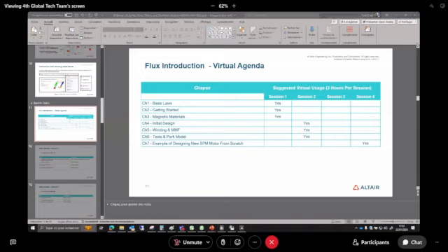Yeah, I have a question from Mayur. What about the mechanical stress? How do we check that? Suppose the rotor is rotating at a certain RPM, how do we check that? Yeah, the mechanical stress is something we don't bring directly inside Flux Motor, but you can test it with OptiStruct, another solution we have within Altair, or SimSolid as well. You can compute the mechanical stress with them.